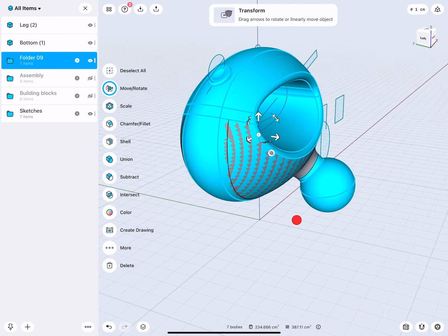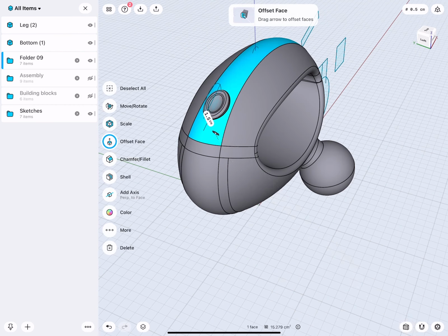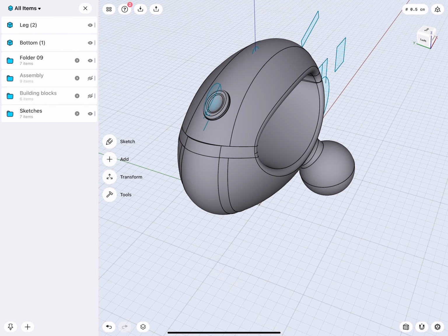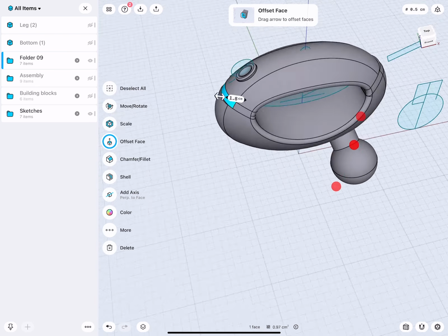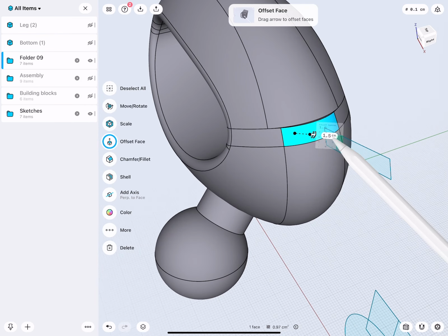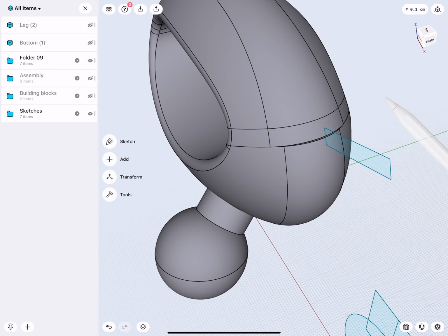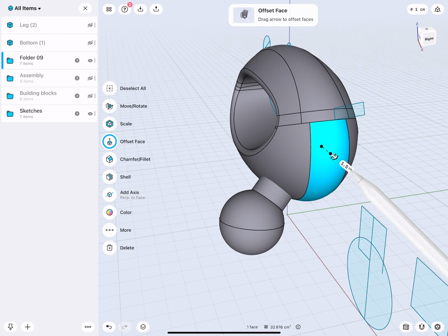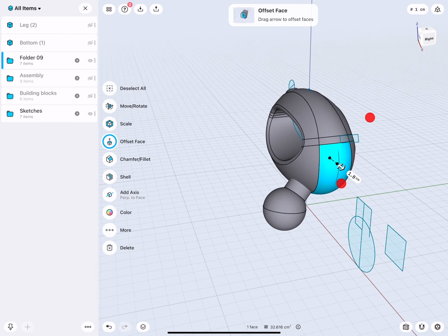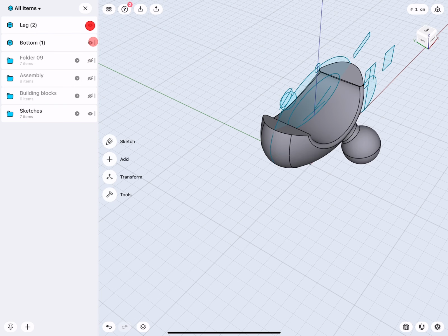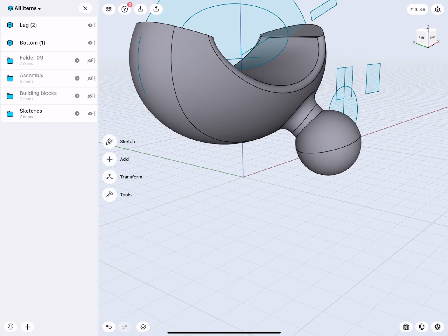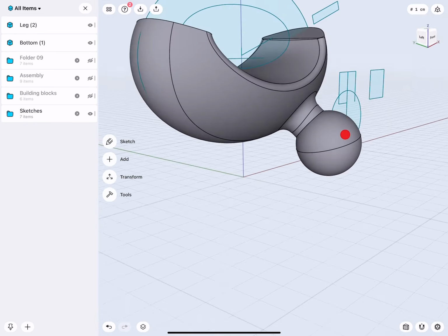Let's actually turn this one on, and here this fillet we set to 1.8. Now we need to make this consistent, and then the same also here. This is a very good demonstration to show how great direct modeling adjustments actually work in Shaper. Very good. There, perfect match. Very nice. Okay. So we transferred the changes over to our original copy. So this is fine.